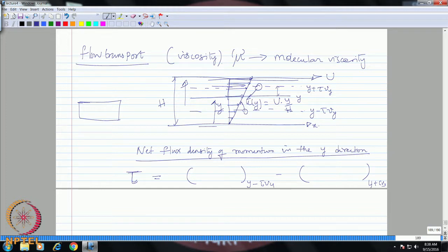because the stress is related to the gradient of the velocity. So, here we have a gradient in the vertical direction. So, that will cause a shear stress on the plate, correct. So, therefore, in order to calculate this stress, we have to find out from the molecular picture, how this velocity gradient is now bringing in a momentum flux change.